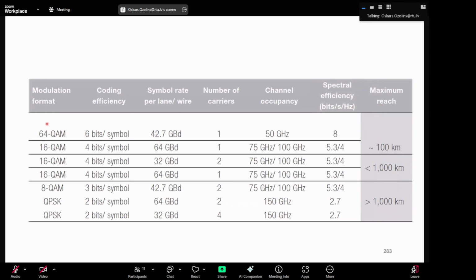Because the spacing between these symbols is smaller, and if we have longer reach, then we get accumulation of noise, and then nonlinear effects also start to play a more significant role. Then these constellations start to get warped, and outer points get more rotated than the inner points. So it looks quite funny. I think maybe you can even see this in your Python simulations.